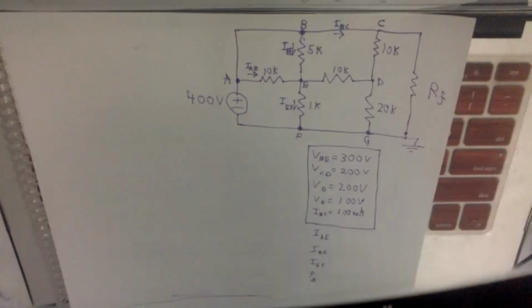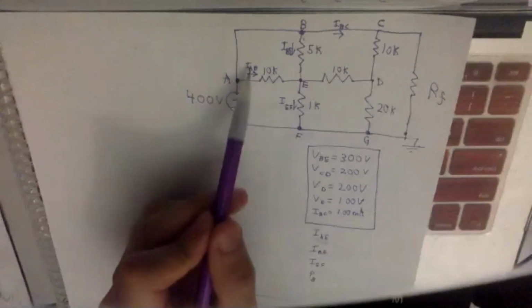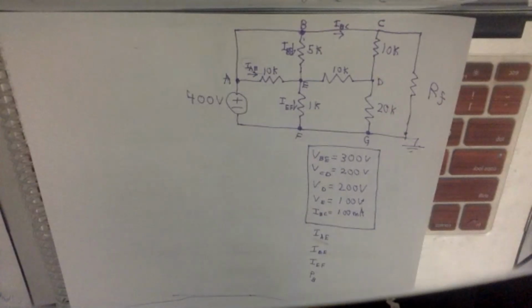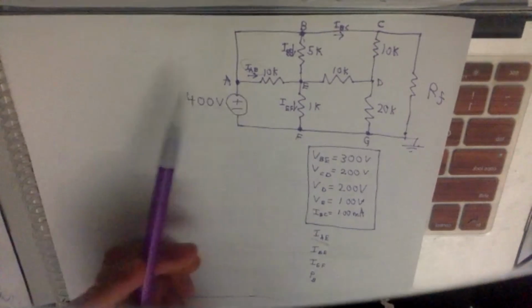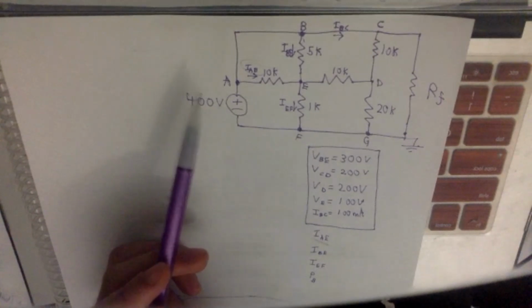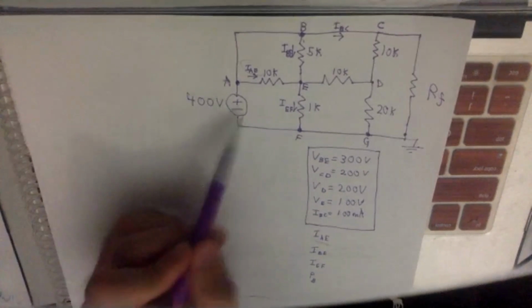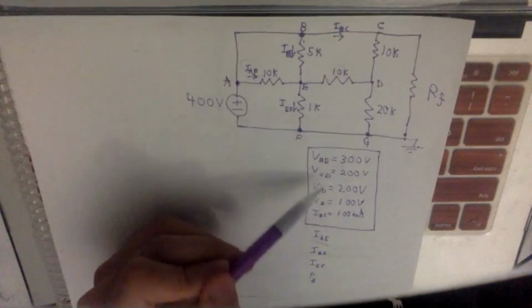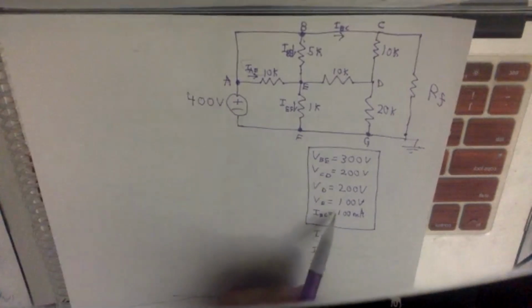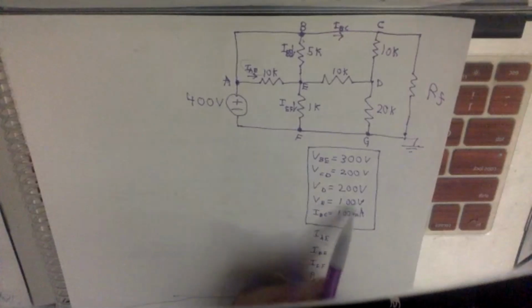All right, cool. So the next problem, number 8, we're going to be looking for this one, IAE, which is right here. How are we going to solve this? We can approach this like V equals IR, that's a really common one. Or in this case, KVL, right? You have 400 right here, and with all the givens, you're going to have VE equals 100 volts.